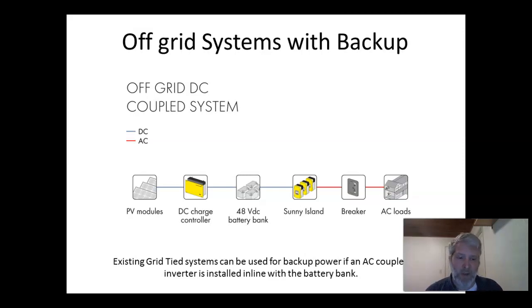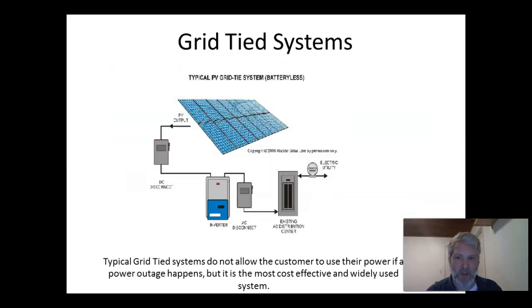So pretty much everybody, when they get solar, says, well, why would I want to have a battery backup system on my grid-tied system? Because when the power goes out, I'm still going to be able to run. Unfortunately, that's not true. Our grid-tied systems are designed to protect linemen that are working on our service lines, and so we have this system called anti-islanding.